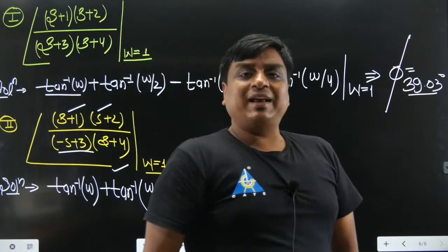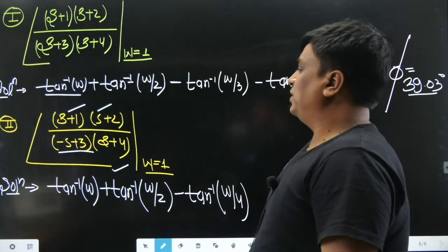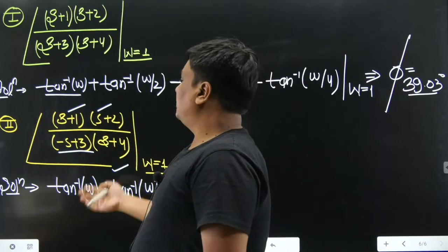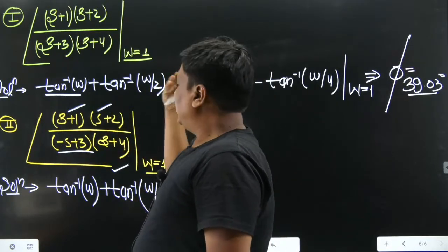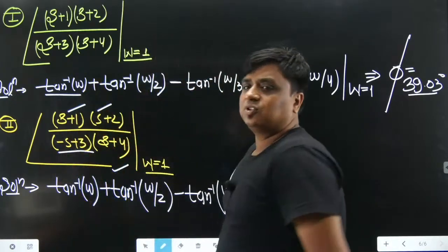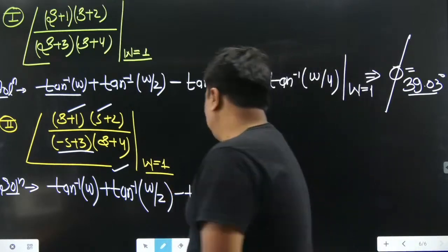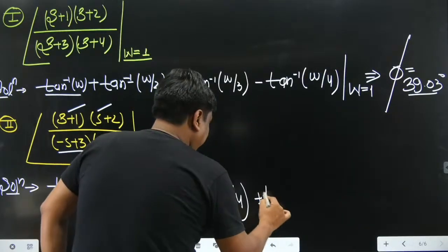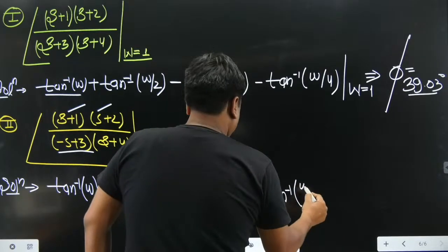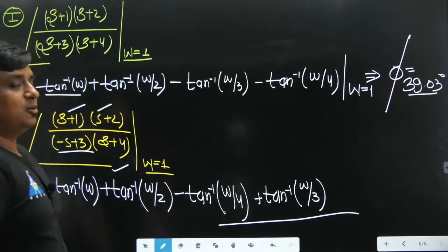Again, the complex conjugate has to be taken, as I have communicated earlier. Because of minus s plus 3, what does it become? 3 minus j omega. Once you take its complex conjugate, it goes to the upside and gets multiplied as 3 plus j omega. And if there is a multiplication by 3 plus j omega, how much angle would be offered by it? That being known to me, it would just be additive in nature and simply be tan inverse of omega by 3, and this has been the outcome.